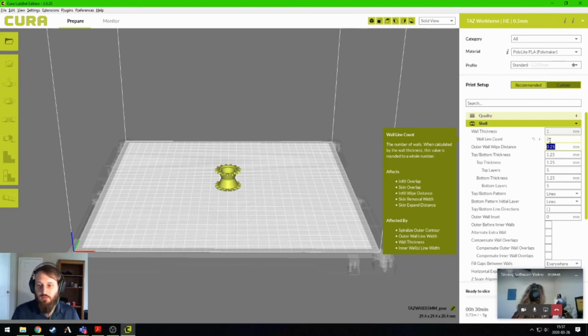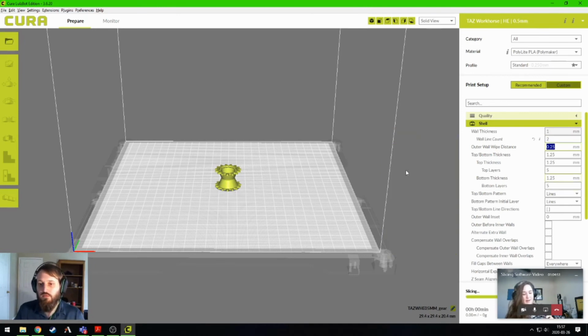Again, like this egg that I printed out. If you want an example of something where you don't want infill, but you want a sturdy object, this egg is pretty solid. I think I put it at like 8 walls or something, but it has absolutely no infill inside of it. So, I mean, it's a sturdy object and you don't have to worry about all the added stuff on the inside. There you go. So you can change these settings within here.